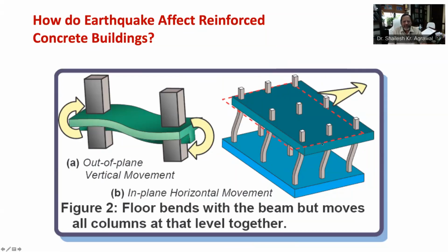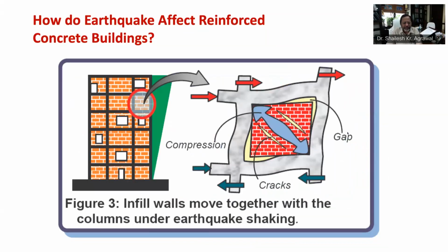In most of the buildings, the geometric distortion of slab is negligible in horizontal plane, and this behavior is known as rigid diaphragm action. As engineers, while considering earthquake resistant design, this action must be taken into account. Now let's see the walls.